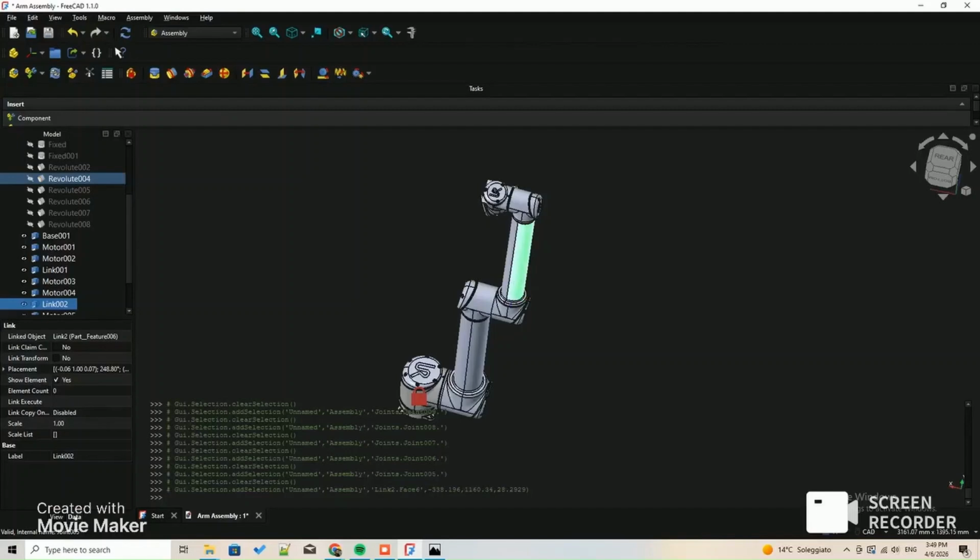So we're moving into the ROS ecosystem. ROS stands for Robot Operating System, and it essentially is used to control the robot and let the robot parts, the brain and the body, talk to each other. So today I'm going to attempt to export a URDF file, which is a necessary file to import it in a physical simulator.